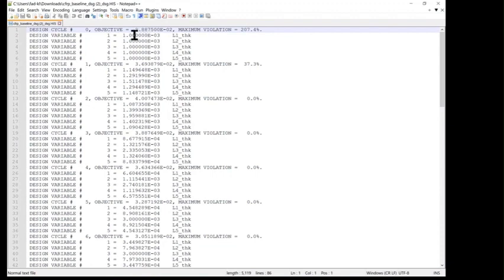And you can see initially we set all of our layers. Remember, our layers, not our plies. So our layers are 1 millimeter thick. Each ply is 0.2 millimeters. So therefore, we're suggesting that there are 5 plies in each layer, i.e. this thing is 25 plies thick.